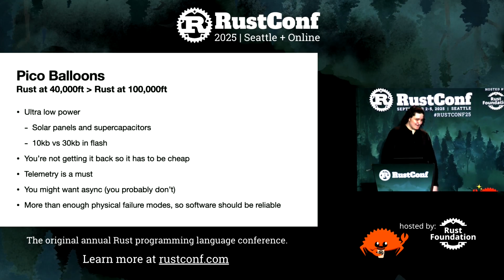Telemetry is a must on Pico balloons. You're not getting the SD card, so you have to send the data, and that gets really complicated unless you're bringing in a library to do it for you in Arduino. You can bring a library in to do it for you in Rust too, but if you want to write your telemetry code, Rust lets us define our data a little better.